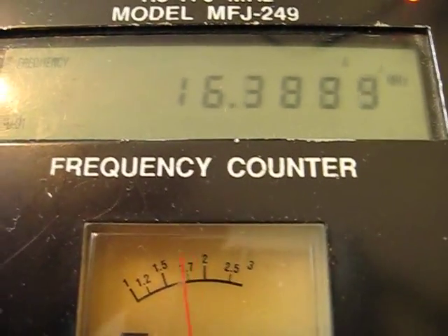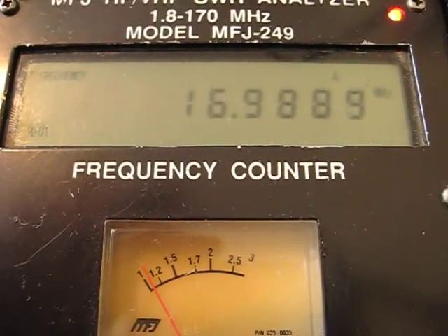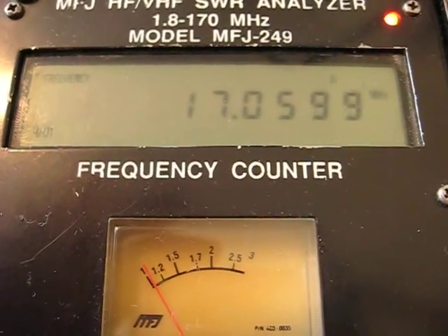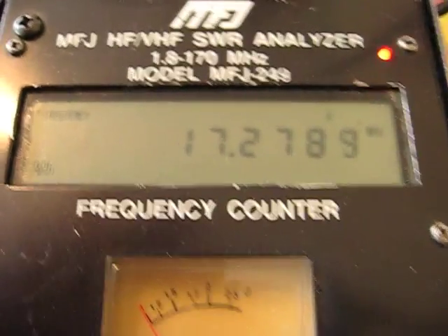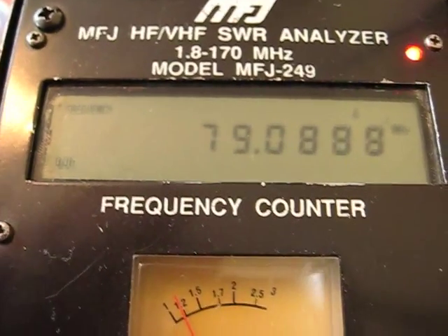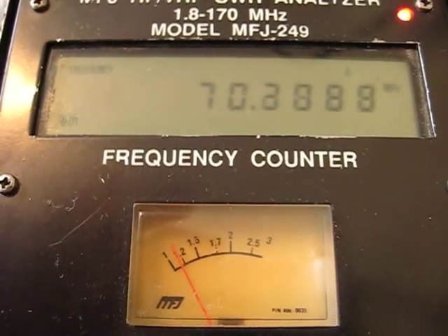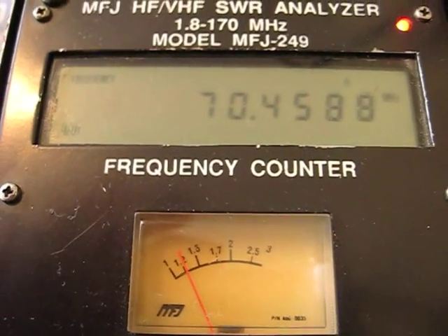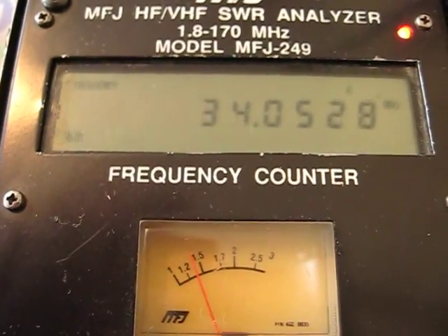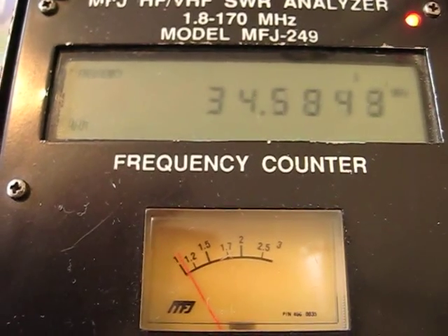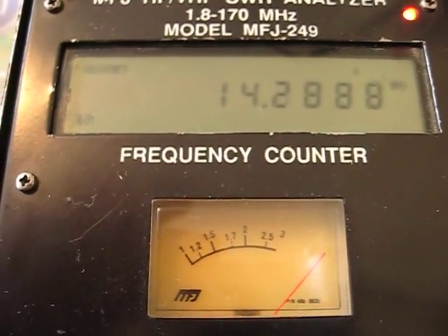So this piece of length it's lying out on the floor, it does have on one end a choke already made on the same coax, but there it is, it's multiples of half a wave at that frequency, and unbelievably it's also near enough to use on 70 megs, so we're on there.